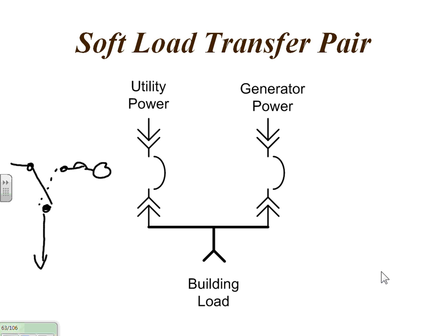Once the generator's up to speed and frequency, the sensors here again see it and say, bring me the power, so it switches. And since you're thinking like that, you might also need to remember that any transfer switch has to operate off the power of the source that it's transferring to. Make sense? Answer your question? Anybody else?